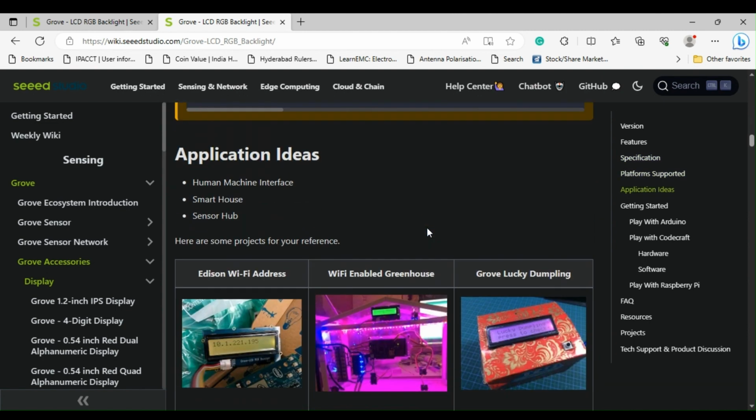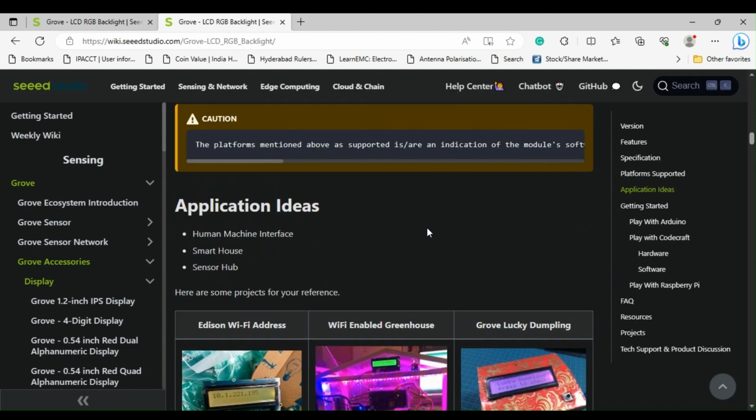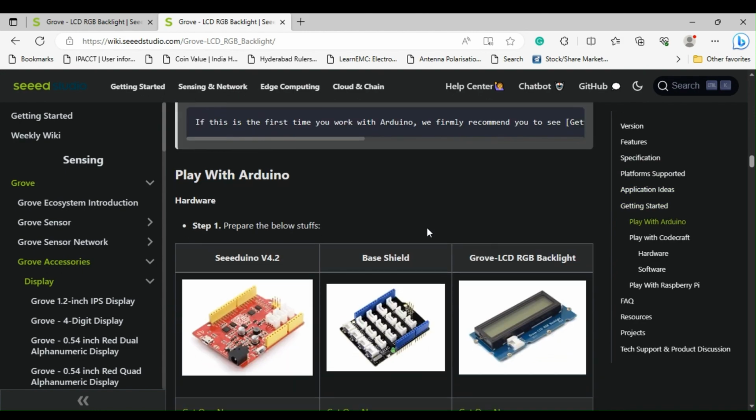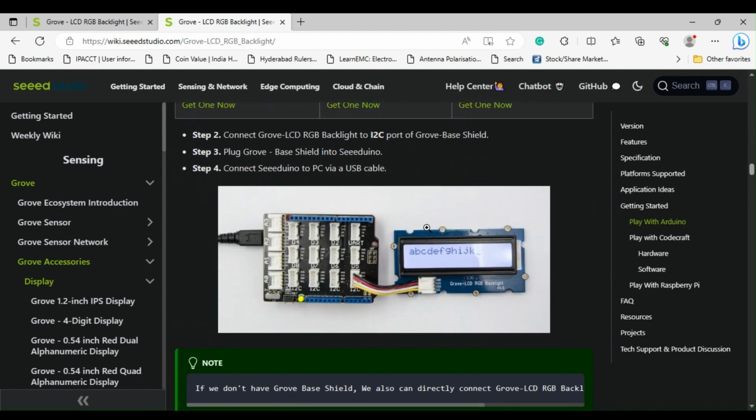As we could connect several devices on one I2C bus, it might be convenient to use a Grove base shield as shown. The Grove base shield fits on the Arduino UNO I/O connectors and therefore has the same form factor for the Aries 3.0 board too. It has 4 I2C connectors. It is very easy to connect all Grove sensors and devices using a connector cable.